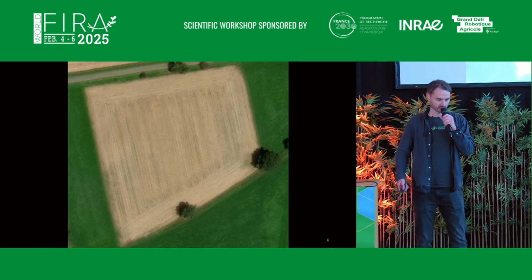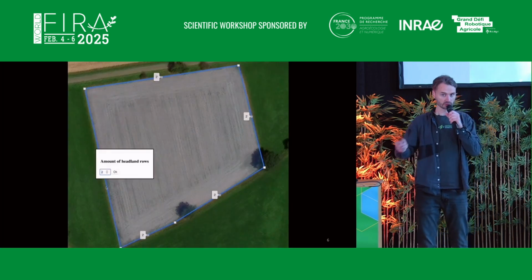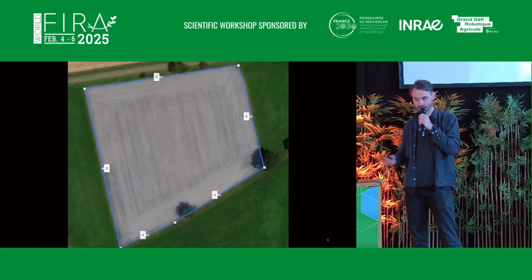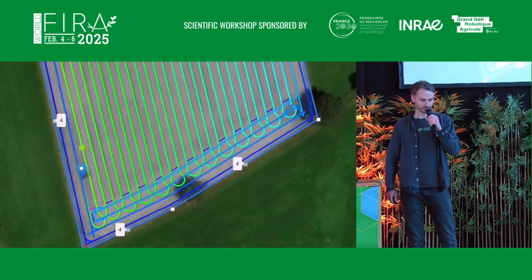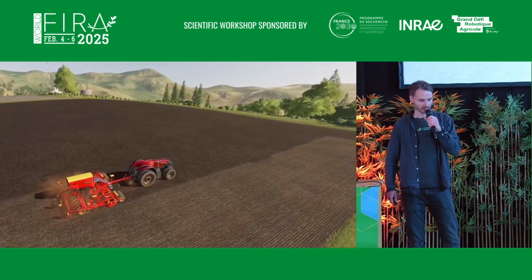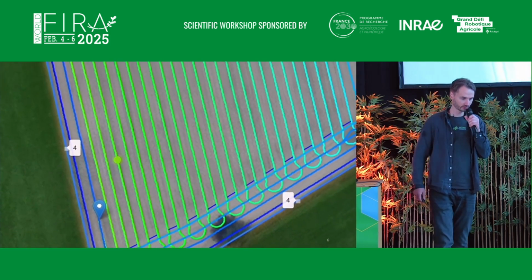So this is, for example, a short glimpse into what we mean when we talk about field coverage planning. So you can draw a polygon, or you can measure your points with some tool on the field to have it more precisely, and then you can adapt the headland size, and then it's planning the complete route in seconds, and the robot can follow also with complex turning maneuvers, and with a precision of 0.2 centimeters, so 2 millimeters of the controller.